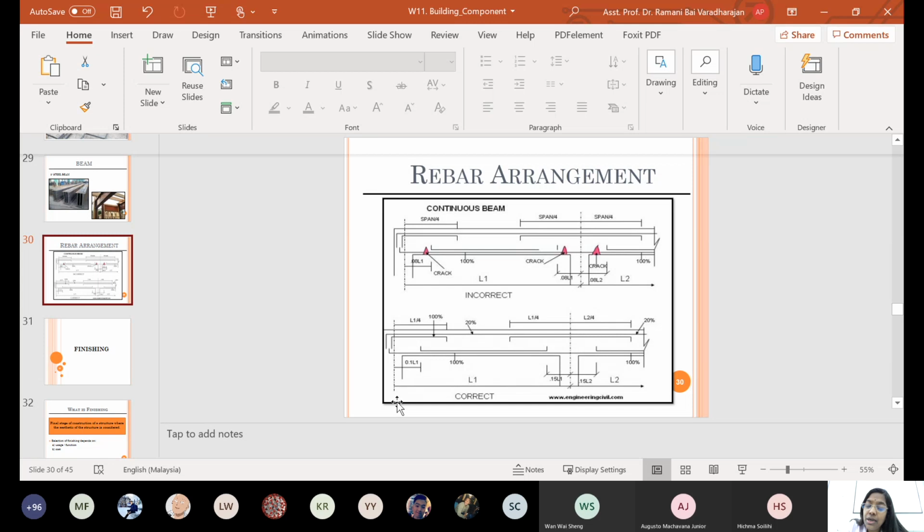No, drawing, you are right, as the sketch will be the same. All sketches will have the size of the beam, size and position of the main rod, size of the secondary bar, and the cover. The overall sketch will be the same, but the values will vary. Okay, so if I have L1, I place it into 0.1 L1, calculate the value, put it there, and do the same for everything. Yeah, the sketch is similar.